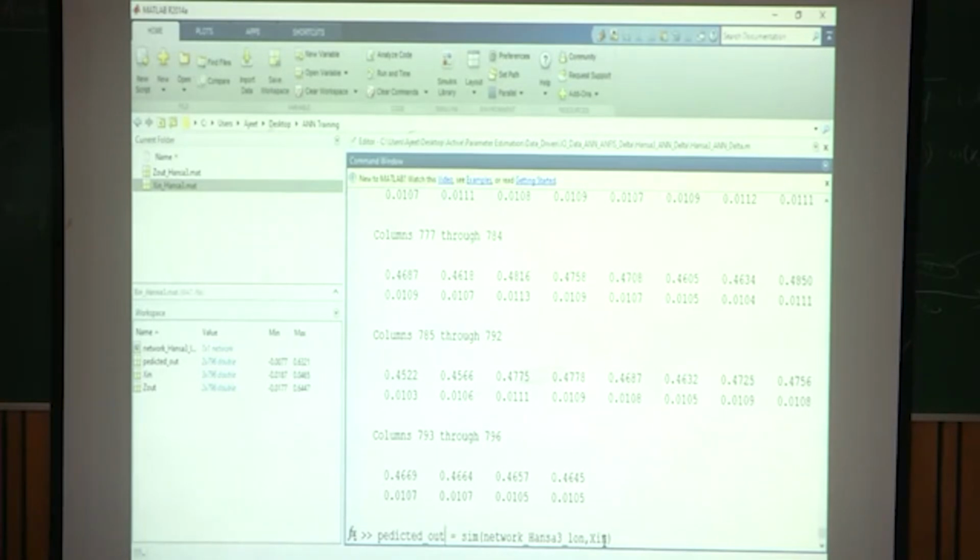Again you perturb in the negative direction, maybe x in minus delta alpha, keep a different name with different variables, store it. Finally, from the delta method, if you want to find CL alpha, it will be your predicted output for the positive perturbation minus the predicted output for the negative perturbation, divided by twice the perturbed input, which will give you the corresponding CL parameter.